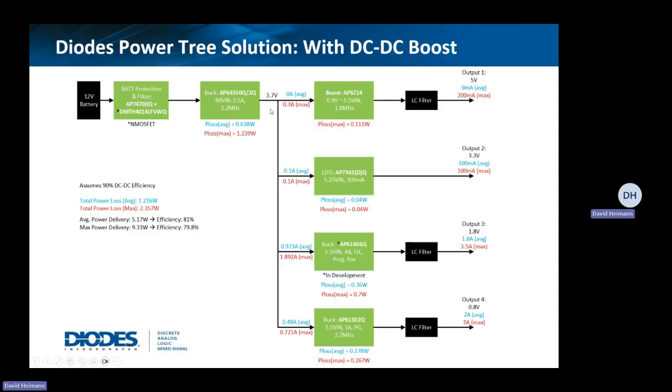So when I was designing power supplies, the conventional way was always to take a look at the highest voltage rail that we had in the system, which in this case is this 5-volt rail here. And we would do this first buck down step from 12 volts. We would typically buck this down to between 6.5 and 7 volts typically, so we have enough headroom for the converter. And if we were to do that, that would create a much higher difference between input voltage and output voltage for these two, where the most power is being consumed in this particular design, right?